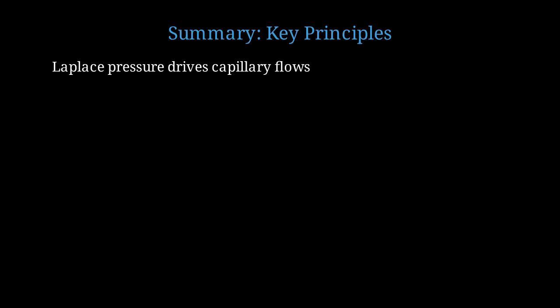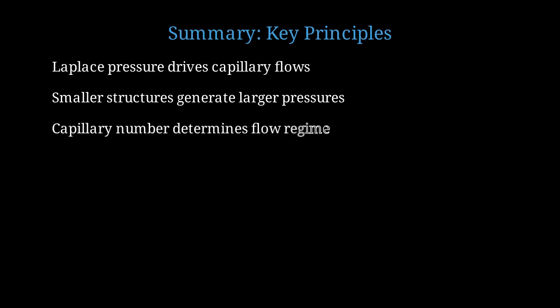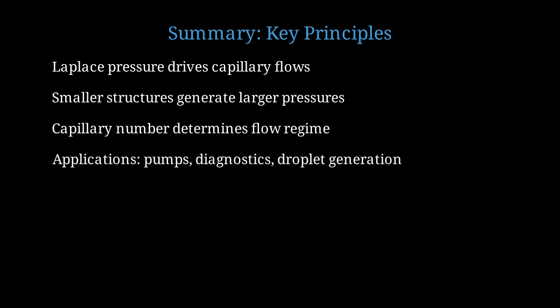Let's summarize the key principles governing capillarity and microfluidic motion. Laplace pressure, scaling as 2 gamma over r, drives spontaneous capillary flows in microchannels. Smaller structures generate dramatically larger capillary pressures, making microscale ideal for surface tension dominance. The capillary number determines whether surface tension or viscous forces control the flow behavior. These principles enable passive pumps, paper diagnostics, and precise droplet generation without external power.